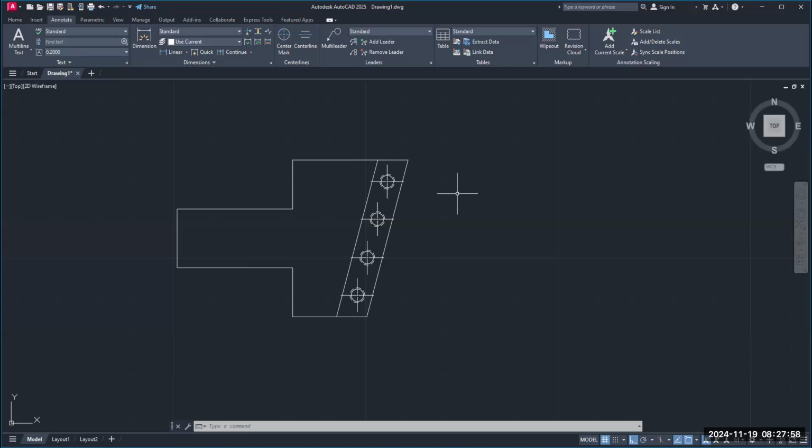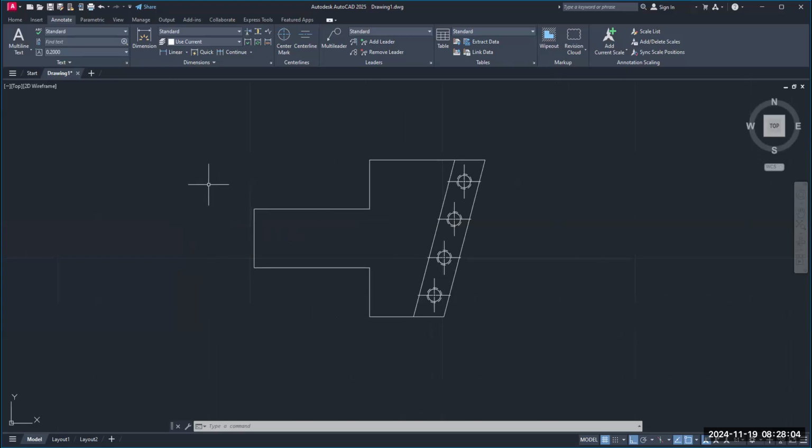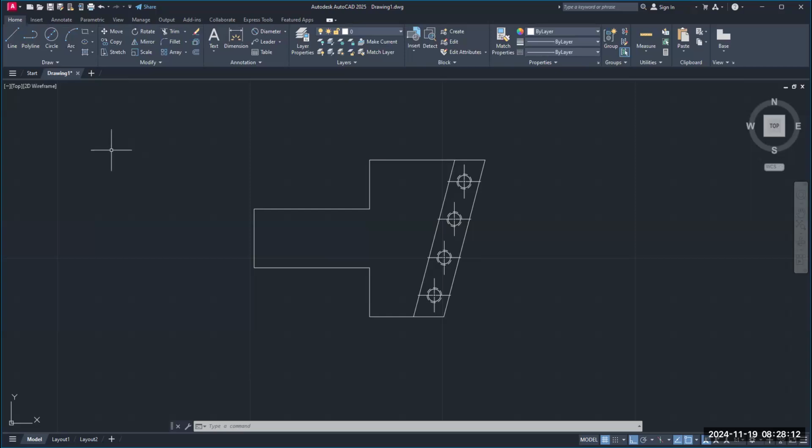All right, we're gonna work on some other parts now of this fly cutter. I want you to go back to, on your menu bar up here, go back to home. Okay. And on your menu bar, under modify, you'll see fillet. Well, arrow down and don't select fillet.